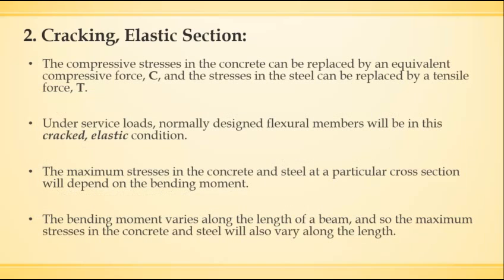When the crack develops, there is a sudden increase in the maximum stress in the concrete and steel. The compressive stress in the concrete can be replaced by an equivalent compressive force, C, passing through the center of the concrete stress distribution, and the stress in the steel can be replaced by a tensile force at the center of the steel.